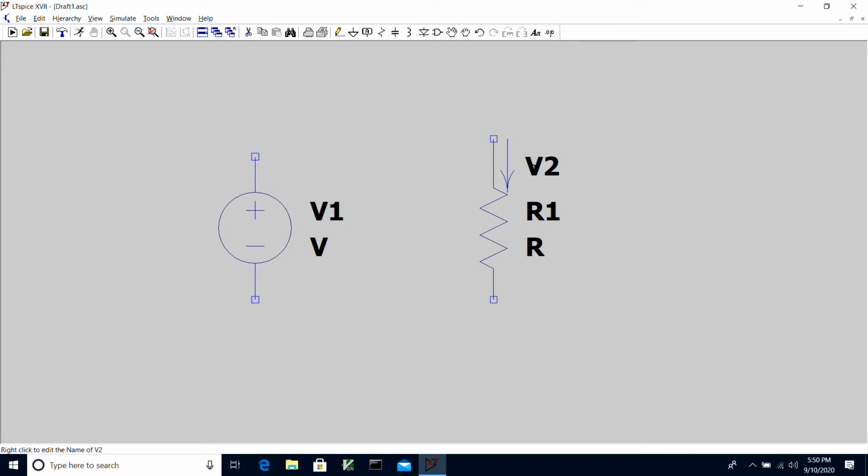And when you click on the voltage source, LTspice will basically report the amount of current flowing through the voltage source. And this was originally the only way that we had of probing the current flowing in the branch of a circuit, was to put a voltage source of 0 volts in series with that branch, and then print the current flowing through that voltage source. But now most modern versions of Spice allow us to probe each terminal of the device and see how much current is flowing into the terminal. I actually find it quite helpful to have these little current arrows in my circuit that I can probe.